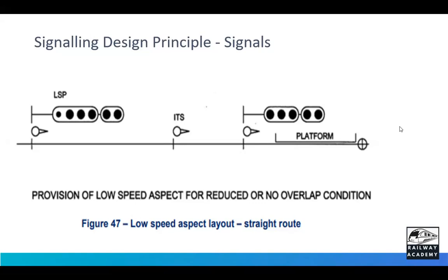So in slow speed areas where train stops are used, it will be just after the signal, and if the signal is red, this train stop will have a mechanical arm raised above the rails, and the train engine tripcock will hit it, and the onboard equipment will get the information that it has passed the signal at red, and immediate brake application will take place.